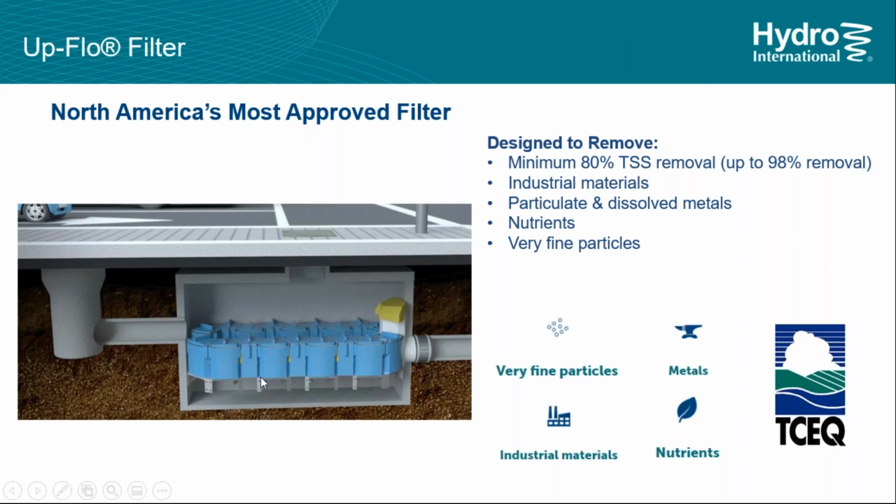Once the larger materials have been removed, water is forced up through the modules, of which there's a channel at the top. So water comes up through the media, the membrane, to the channel, which it can move downstream. And that is how we treat the first inch, inch and a half of rainfall, the intended treatment flow. During larger storms, your 100-year storm event, shown in yellow here is a bypass hood. As the water elevation in the system gets up to here, it acts as a snout, so it won't pass the floatables or the oils, but it will go into bypass and let water move downstream.